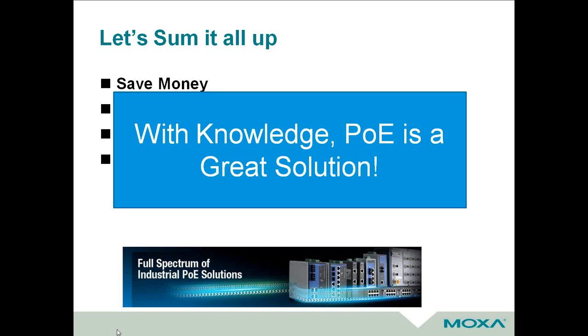Can you explain why 4 wires for power? Sure, that's an easy one. And Simon, thank you for all the good questions. Obviously, PoE is of great interest to you. The 4 wires for power is simply because most Cat5 cables are running on 28 gauge wire. So it's pretty thin.